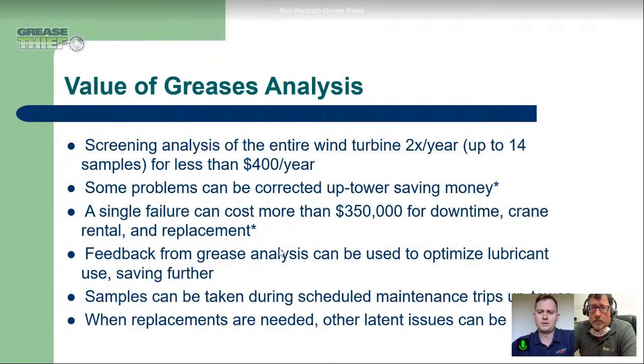Speaking specifically about the grease lubricated components, such as the main bearing, there's things you can do like hot oil flushes periodically in order to purge some of that ferrous material out of the bearing to prolong the life. There's plenty of other mitigation techniques as well.